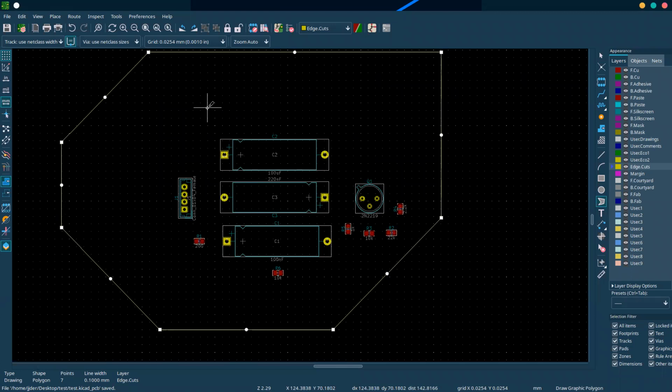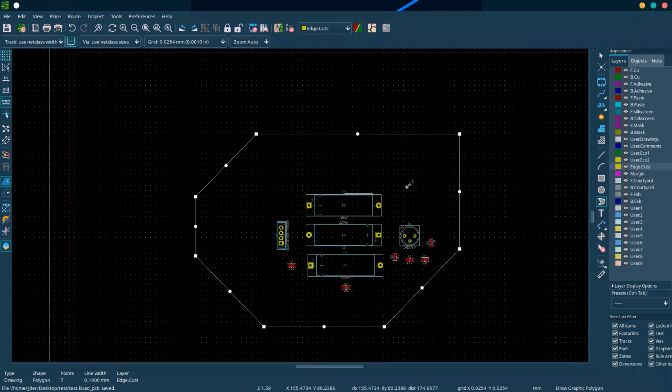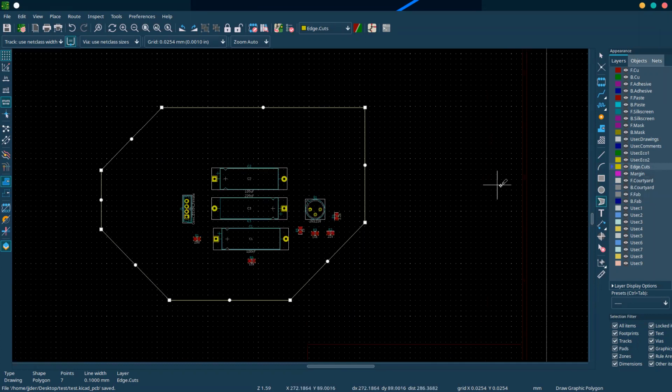Is that working for everybody? Good. Okay, this part isn't really that important. So if you're falling behind, just put a rectangle there on edge cuts and call it a day. What was the draw tool? The draw tool. Oh, yeah. So select edge cuts on your layers, and then it's any of these lines. Okay. Yeah, anything you want. Yeah, I just went crazy around.